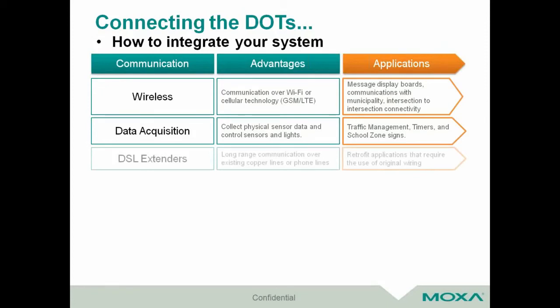DSL extenders allow you to communicate on both sides, but you have your Ethernet communications. So essentially, that gives you room to do retrofit applications at decent speed. If you're transferring signal data, you're transferring about 50 megabits per second. It's not ideal, but it's enough to get that data if you need it without pulling out the whole system.